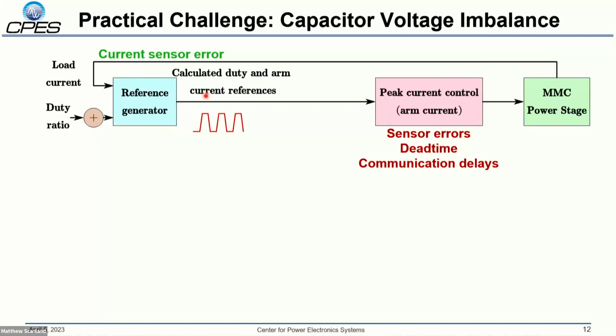To demonstrate this idea, we operated it at 7.5 kV and each PEBB is maintained at 2.5 kV. And if we don't have any closed loop balancing control, the capacitors themselves do deviate a lot because it's very fast control and the PEBB capacitors are chosen very small.